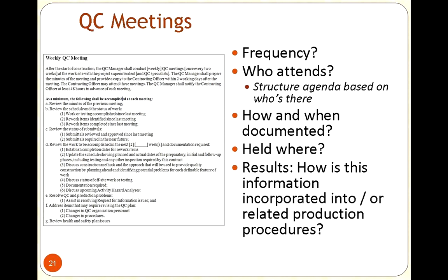And a lot of that might end up affecting the contract. So in these meetings, you're going to be discussing the contract. You're going to be discussing what the scope of work is. And a lot of these meeting minutes will be used if you need to go in and do an addendum to the contract, or if you need to start reviewing if a change order is going to happen. But the meeting minutes are where you need to document them so you can go back and review them, whether, again, it be digital or electronic or hard copy. Always keep them out there.